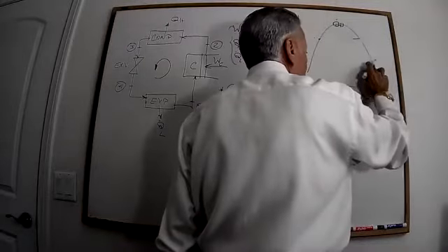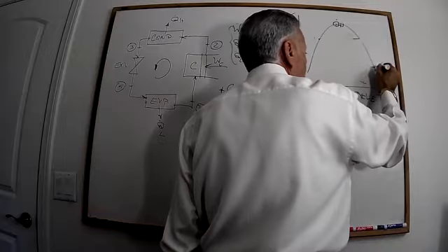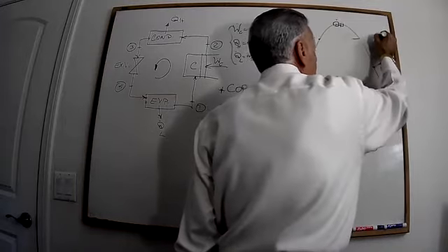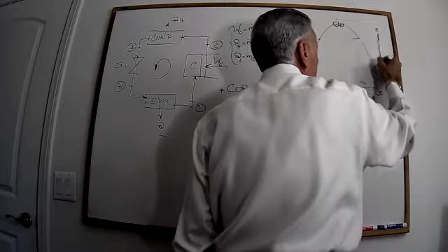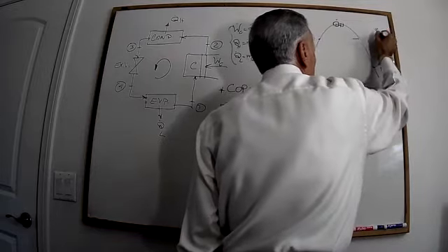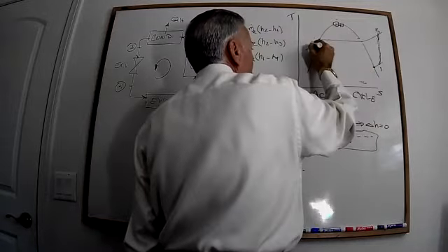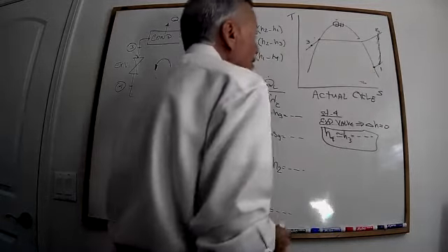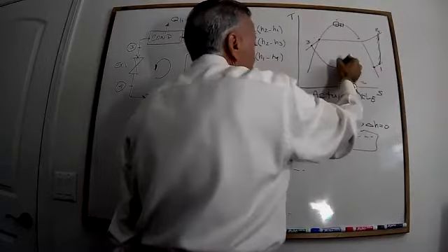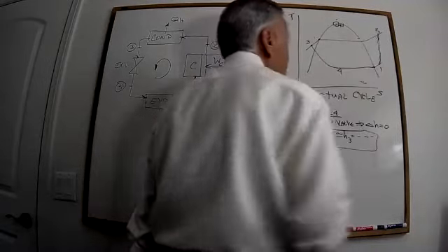Now our point 1 is going to be here in a superheated region. And point 3 is going to be in a compressed liquid. Then you come down again to point 4, connecting it back to point 1.